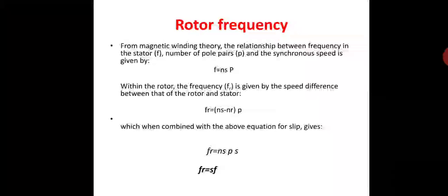It is a very basic question. Sometimes they will ask in university, what is the rotor frequency in an induction machine? If they ask like that, you can write the answer Fr is equal to S into F, and also mention the factors S and F.